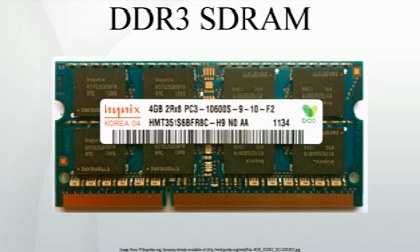PC3-8500E. Modules can be registered, which improves signal integrity, and hence potentially clock rates and physical slot capacity, by electrically buffering the signals with a register, at a cost of an extra clock of increased latency. Those modules are identified by an additional R in their designation, whereas non-registered, aka unbuffered, RAM may be identified by an additional U in the designation. PC3-6400R is a registered PC3-6400 module, and PC3-6400R ECC is the same module with ECC.